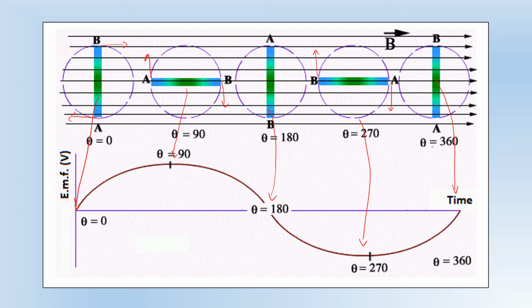So the key thing is whether the side that is into the plane of the page is moving perpendicular or parallel to the field lines. That tells us what the EMF being induced is doing. And the reason the EMF decreases is the number of flux lines per second that are cut decreases as the angle between the velocity and the field lines increases. We cut through fewer field lines per second until we get to 0 when it's parallel.